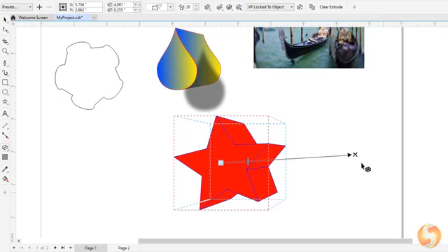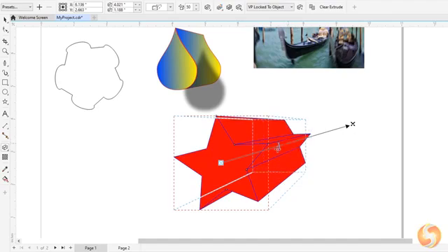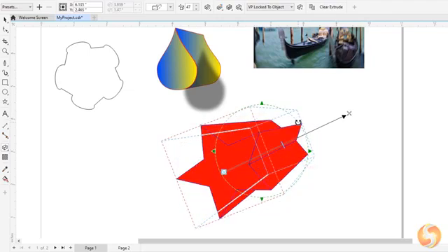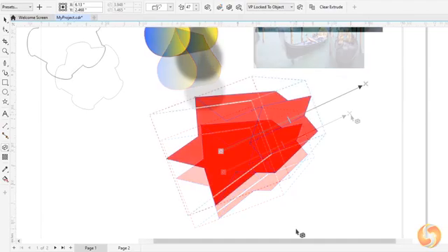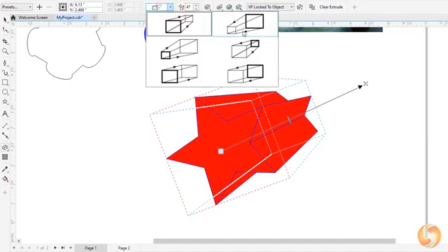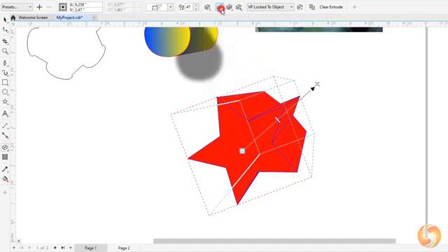You can adjust its direction with the black cross and its total length with the small white block. Always with the Extrude tool, you can click once on the extrusion and click and drag to rotate it, or drag from its green circle to rotate around its axis. Consider that you won't be able to adjust the extrusion direction after this, as you can see from the white cross.